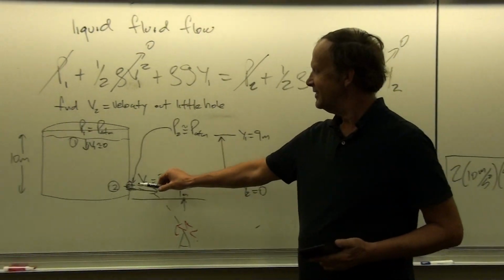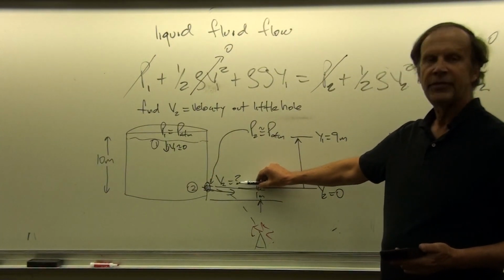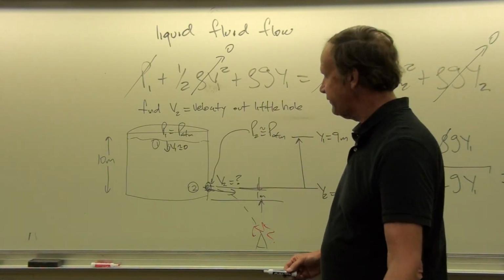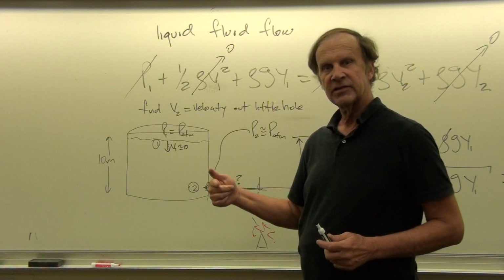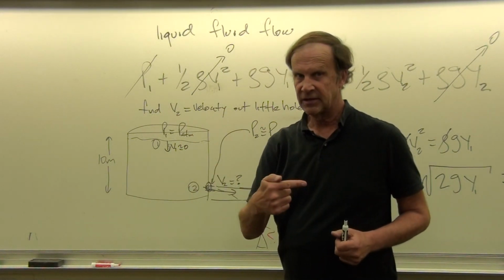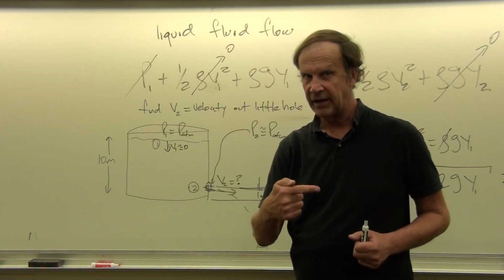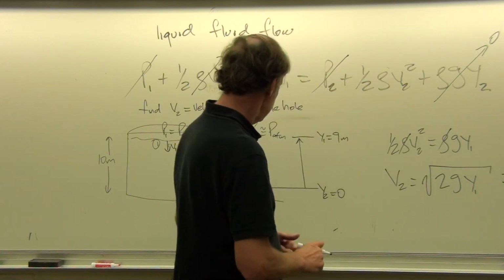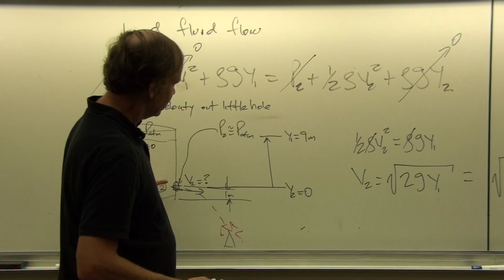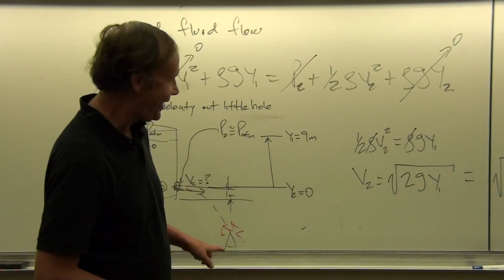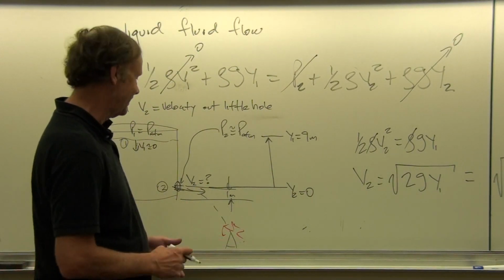So what's interesting here then is that the fluid, as it flows out at this pretty high speed, would have the same trajectory as a mass that's projected at that horizontal velocity. So you could figure out if that's the right height to make the hole so that the water flows down and puts out the fire of this house down here in this complex.